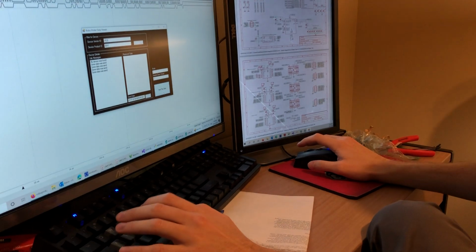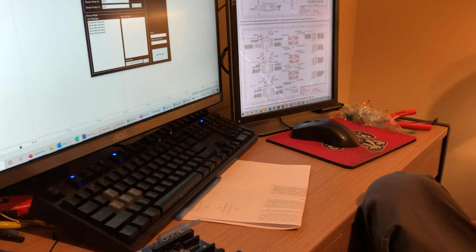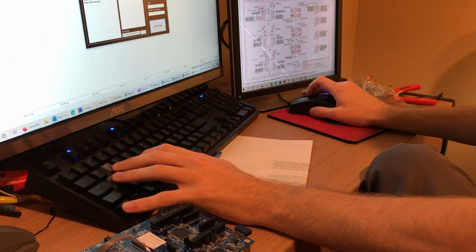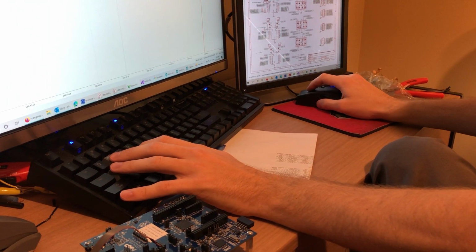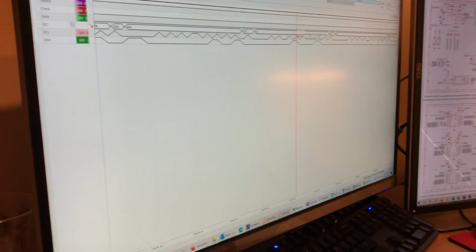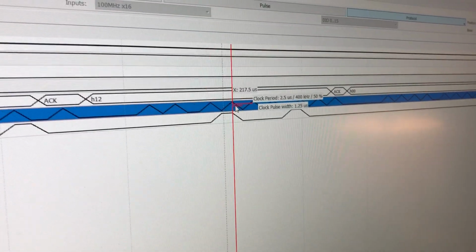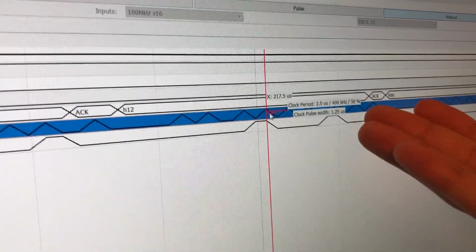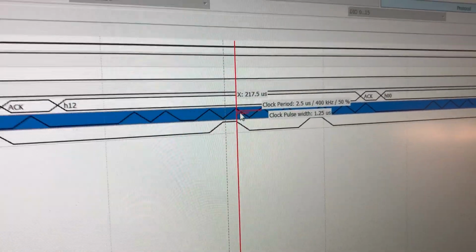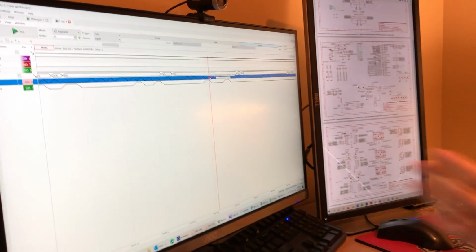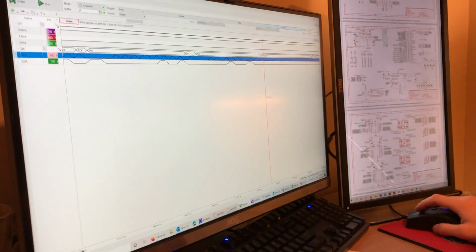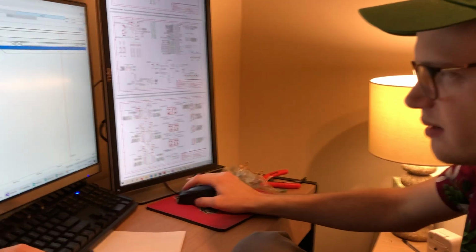So now that demonstrates that I2C works, and let me demonstrate that this is indeed I2C fast mode, which is the highest frequency we said we would be able to do. When you make the measurement on the Analog Discovery 2, it shows the clock is 400 kilohertz, which corresponds to I2C fast mode, the specification in our PSSC.